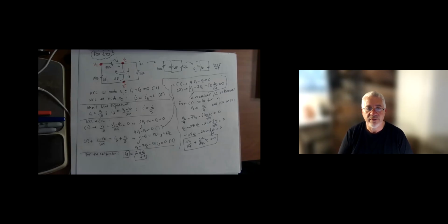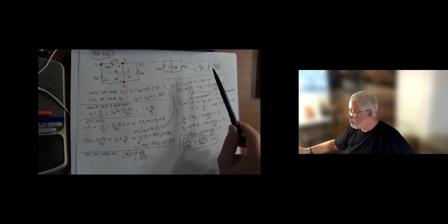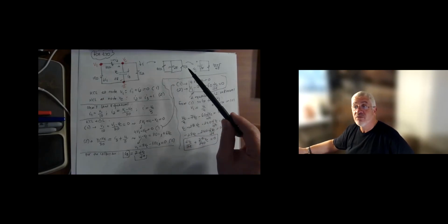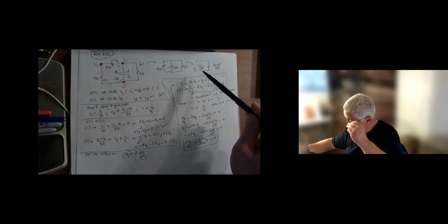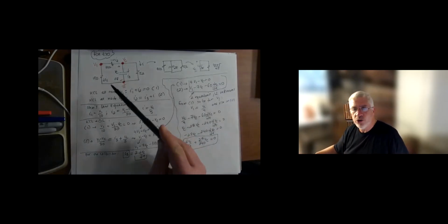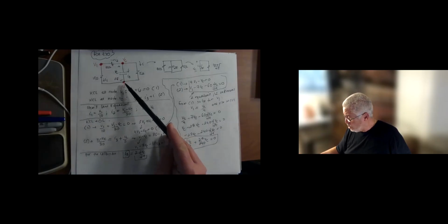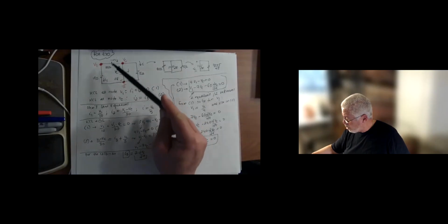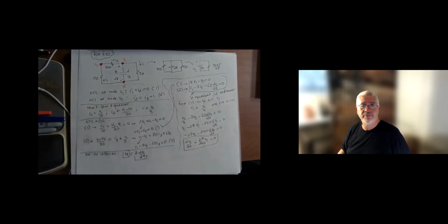Nothing is skipped here. Okay, so I want to take a moment to review what we did here. All right. Again, I purposely chose not to do the combination because many times you won't be able to do this. Although this, you could have easily done it and used the solution we just did. So I basically went on to doing a regular nodal procedure. Find my 3 nodes. Then I select the reference node, label the other nodes, and put current on my passive elements, namely my resistors and capacitor in this case.